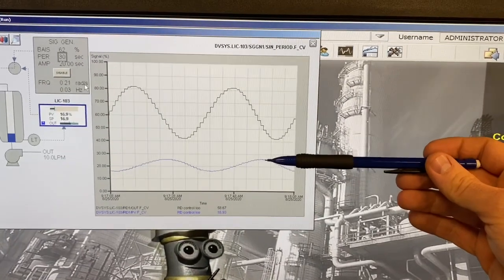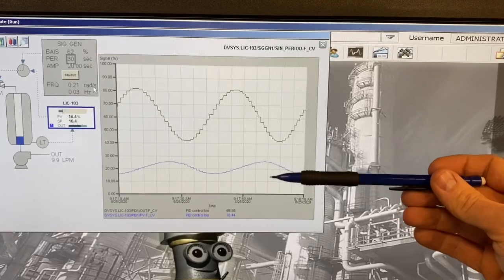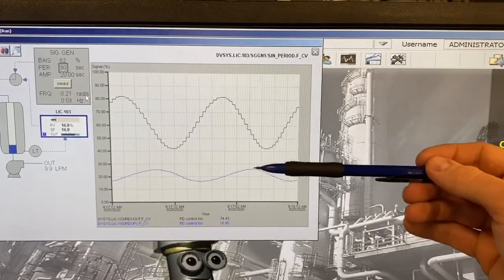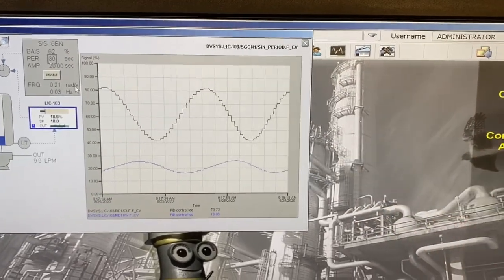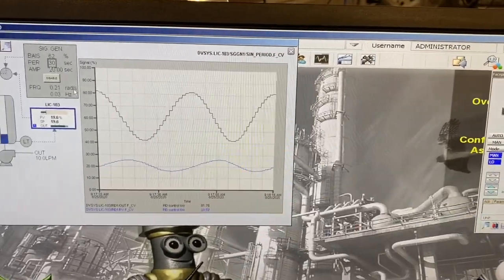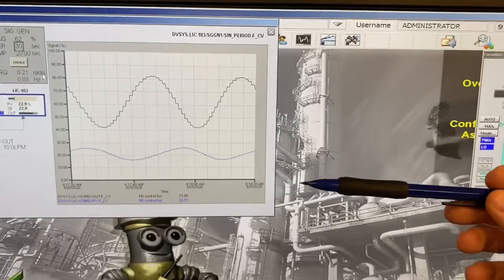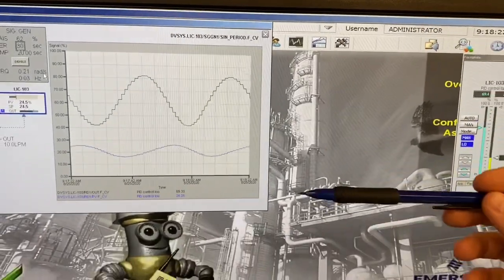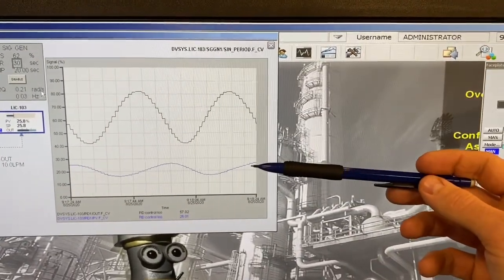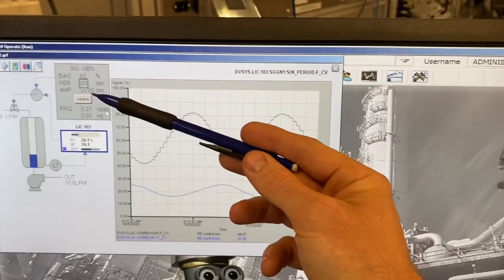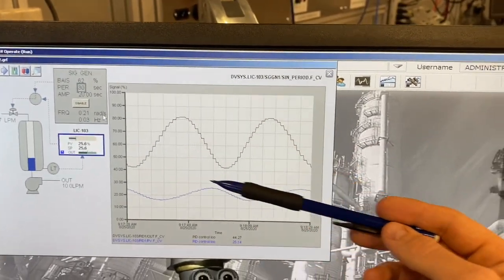But down here now you can see that our amplitude has shrunk. We increased our frequency and the amplitude went down. So that's probably going to indicate that our gain value is going to become less. So let's figure out what our gain value is, get the values to determine our gain value. These are still the same, but now our frequency is different. So we've got a new radian per second value here.